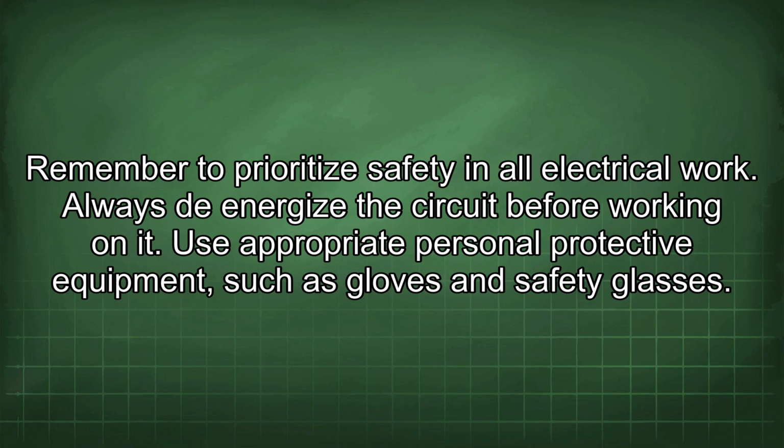Remember to prioritize safety in all electrical work. Always de-energize the circuit before working on it. Use appropriate personal protective equipment such as gloves and safety glasses.